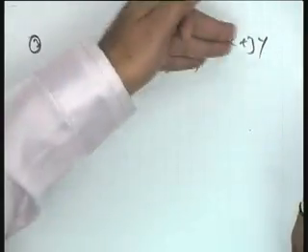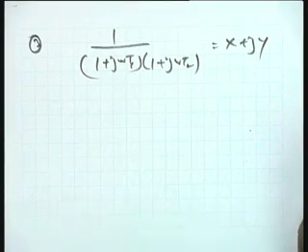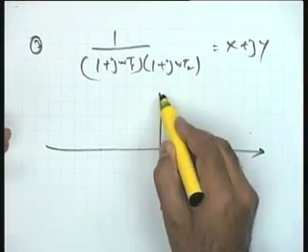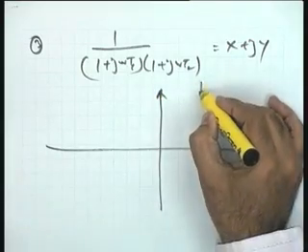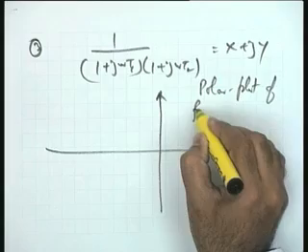Though the answers are available with me here, I think I will save time because this is a very clear picture. I need not give you the intersections with the imaginary and the real axis. So, I give you a hint. My method of working, I convert it into this type of vector and then set x equal to 0 to get one answer and set y equal to 0 to get the other answer. And if you follow this or any other method, you have got what is called the polar plot of the frequency response.